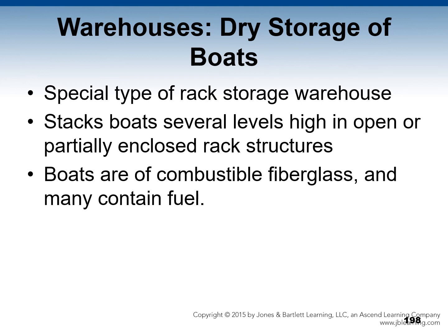Also in warehouses, you have dry storage of boats. These are special types of rack storage warehouses. They stack boats several lengths high in open or partially enclosed rack structures. The boats are of combustible fiberglass in most cases, or wood, and contain fuel. Even if they don't contain fuel, the tanks have vapors. Then you've got other combustible materials in the engine. You have oil, etc.